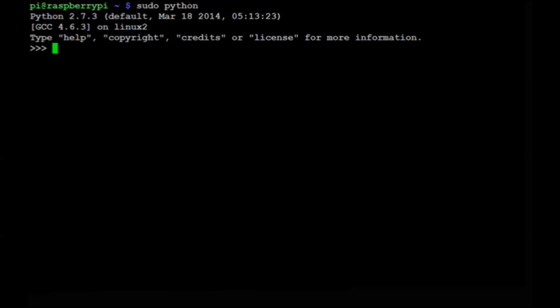The first line of code is import RPi.GPIO as GPIO. This line of code imports the GPIO library into Python. The second line of code is GPIO.RPI_REVISION. When enter is pressed on the keyboard, the console will return the revision number. In this tutorial we are working on revision 1. It is important to check this as the pinouts will vary on each revision.